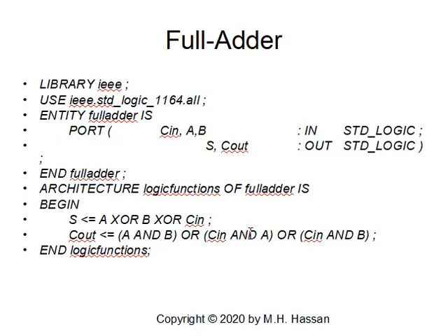Now, if I would like to use the full-adder in a larger size adder, I have 2 approaches. Either I can declare the full-adder as a component within the code of the larger size, or I can package the full-adder, declare it as a package, and I can call it anytime in any program. This is a better and more general approach, and makes life much easier for you if you'd like to use the full-adder in many other programs.